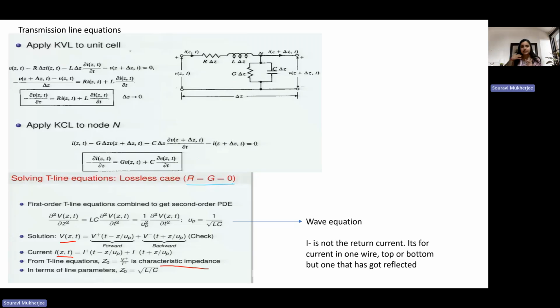So now what is this characteristic impedance? Basically, it means that there's some impedance that your transmission line is providing to the signal. You have some incident voltage, but the voltage sees some effective impedance as it passes through the transmission line. And that depends on how these distributed parameters are, right? And that is the characteristic impedance of your transmission line.